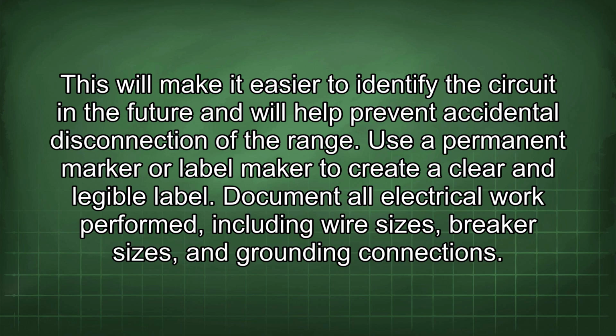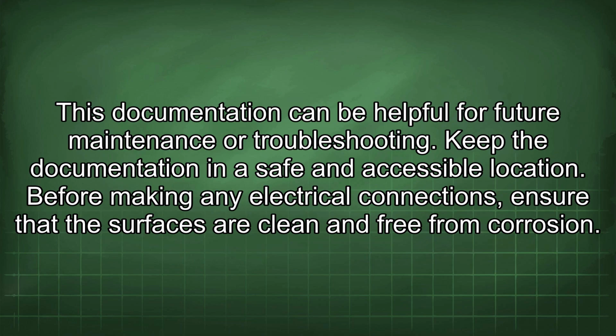Document all electrical work performed, including wire sizes, breaker sizes, and grounding connections. This documentation can be helpful for future maintenance or troubleshooting. Keep the documentation in a safe and accessible location.